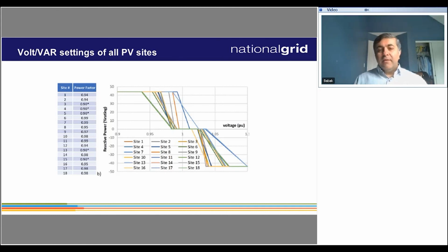So no manpower can manually go to the facility and keep changing volt-var curves every day. That's why we need systems like AGMS or DERMS to remotely monitor the status of each large-scale DER and adjust the volt-var curve based on the available reactive power resources in the system. Otherwise, just one voltage setting, volt-var setting, and power factor setting is going to be extremely challenging in terms of impact on the grid.